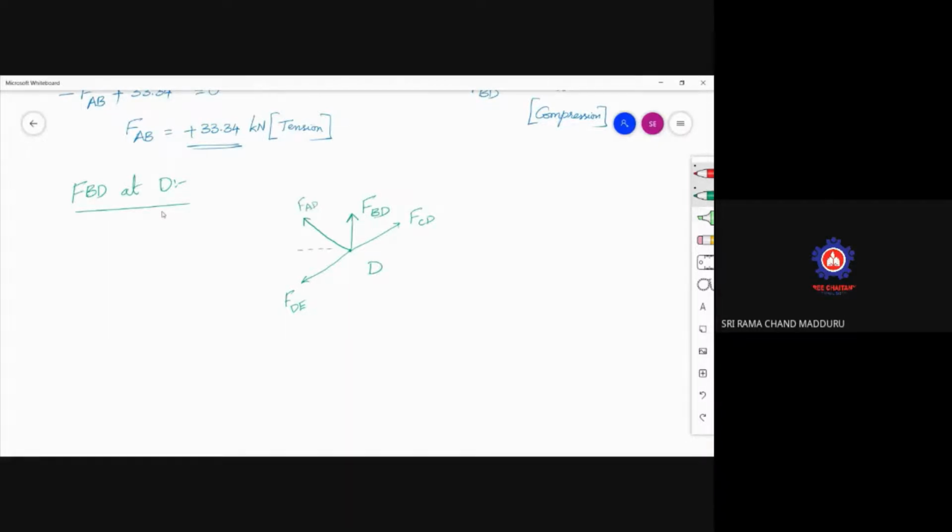So this is your x-axis. At x-axis, this angle is 36.86 degrees. This is also 36.86 degrees. As the forces are inclined, they are to be resolved along the x-axis. So this FCD I am resolving. How am I resolving this FCD? So this will be FCD cos 36.86.